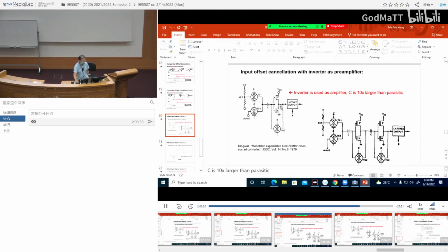You know that this inverter transfer curve is changing for different inverters. I put one inverter here, one inverter here, same inverter, three points. But if you measure the transfer curve, they are not exactly the same, because of mismatch and everything, the curve is shifting a little bit.